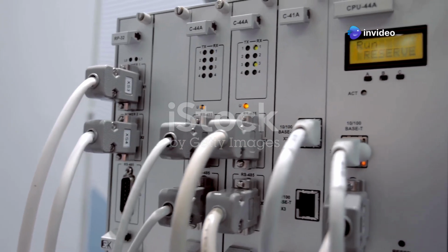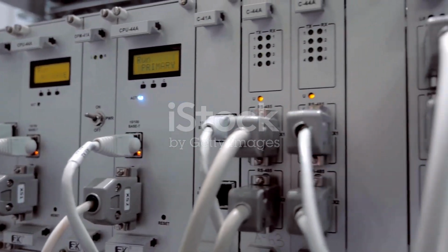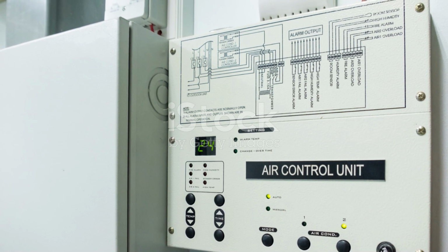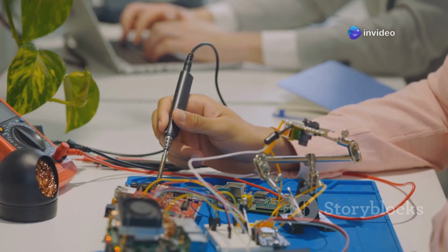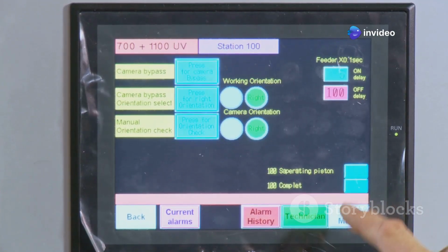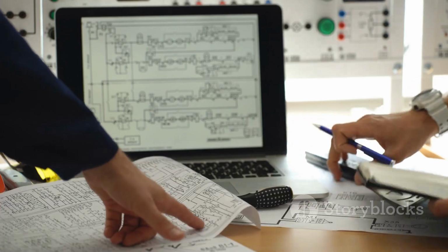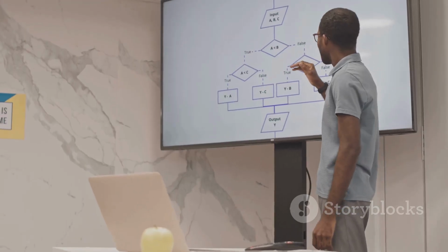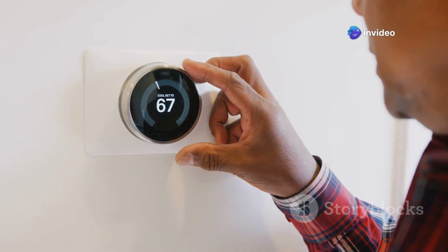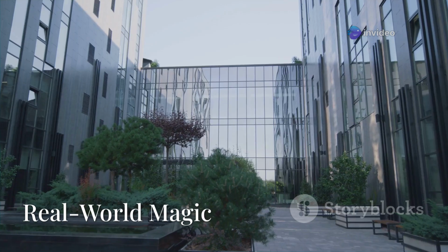The primary control device in most modern building automation systems is called a controller. Often you'll hear it referred to as a DDC, which stands for Direct Digital Controller. Essentially, a DDC is a small, specialized computer. It runs sophisticated software programs. These programs contain the operational logic for the building systems. This logic is often a series of if-then-else statements. For example, if the room temperature is below the set point, then turn on the heater.